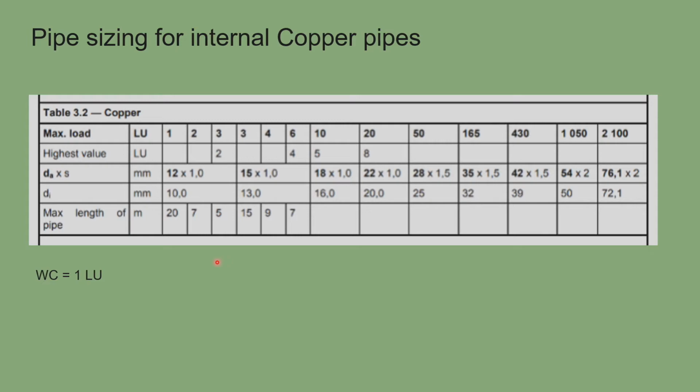Right, so first things first, that was on our list, section A. So that has got a loading unit of 1. So what we do then is go onto our table, we find our max loading unit, 1. We go down and we find our max diameter of pipework, which is 12. So the minimum requirement that this document says, with no sums, no expected calculations, is we need 12 millimetre pipe to supply water to that toilet.